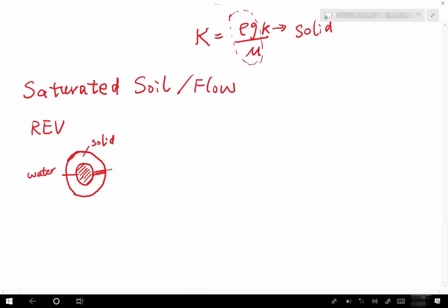And then, in order to derive the governing equation, we need two things again. One is the law of conservation. The other one is this constitutive relationship, that's Darcy's law. So for the law of conservation, just think about what we did before. We learned the general conservation law. We learned how to formulate it using equations, right? The general law for conservation is that the change of a conserved quantity over a unit time, so that's partial something partial t, equals. Let me write down the general equation.